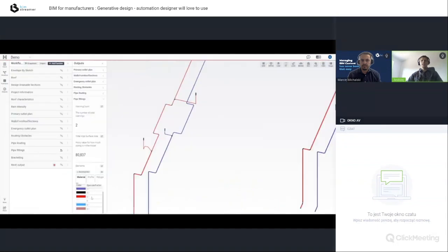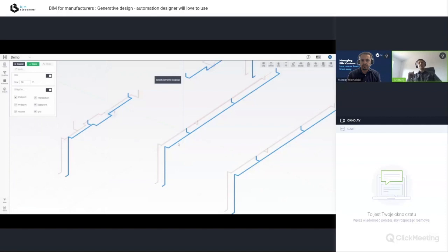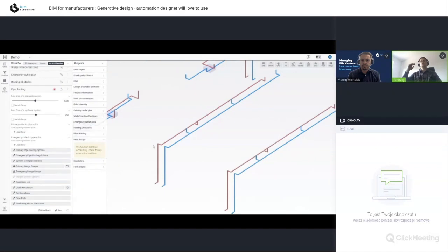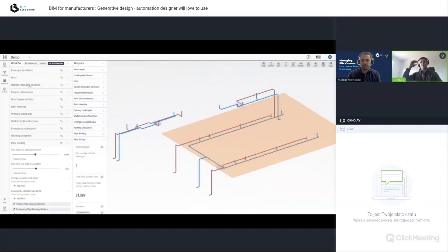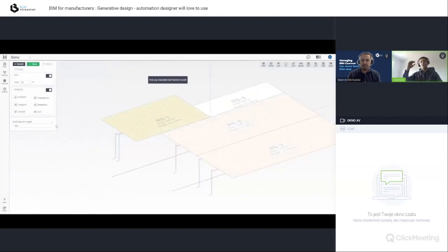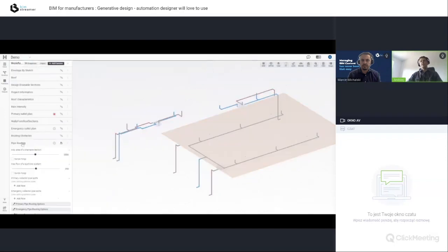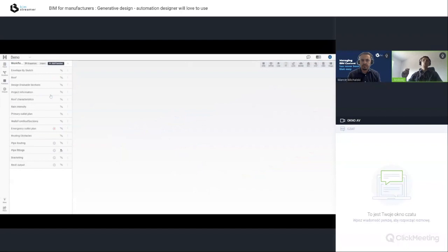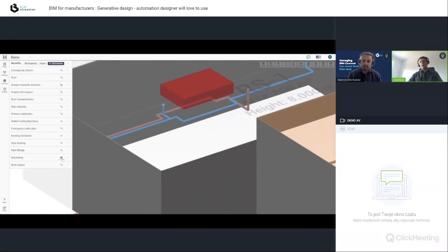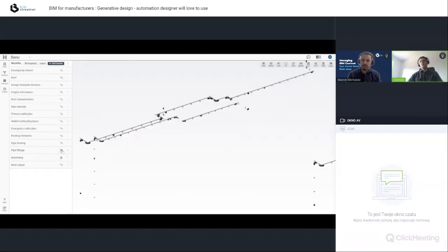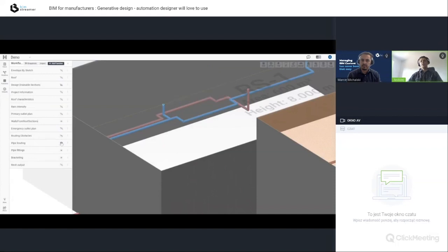What is also nice here is that when we go to the end and we have generated this model, for example here the roof height is very important because the pressure changes. When at the end I move the roof a little bit, normally everything changes: all pressures and pipe diameters change, and additionally all obstacles which are overrides, not automatically generated, are also applied here, and everything is recalculated. Then all changes are done automatically.